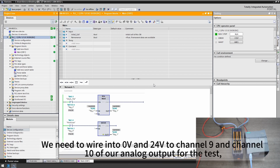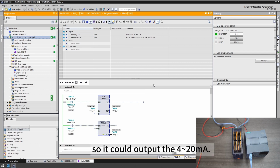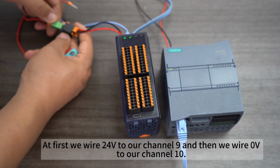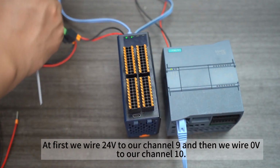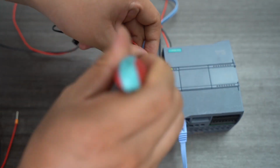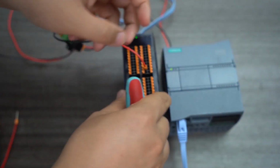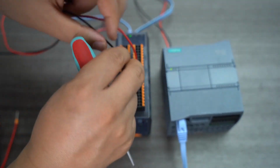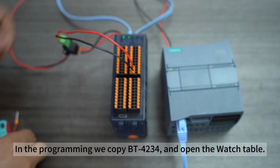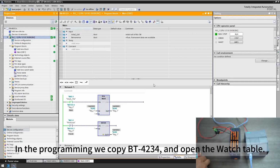We need to wire 0V and 24V to channel 9 and channel 10 of our analog output for the test, so it could output 4 to 20 mA. At first, we wire 24V to channel 9 and then we wire 0V to channel 10. In the programming, we copy BT4-34 and open the watch table.